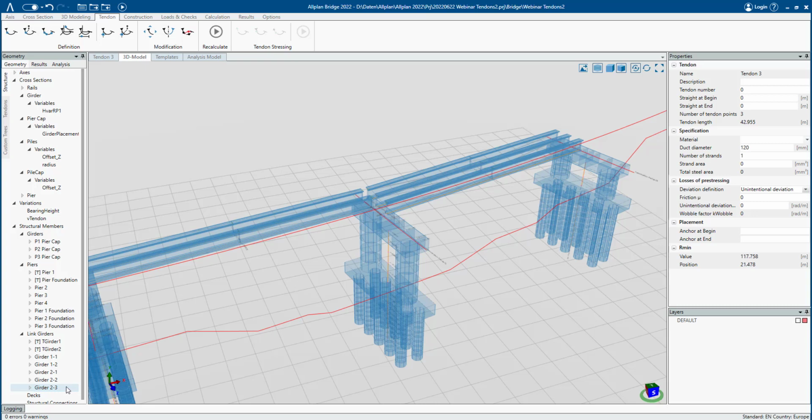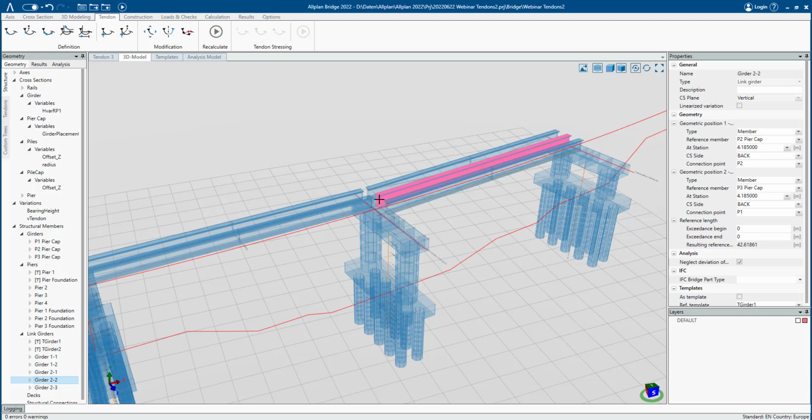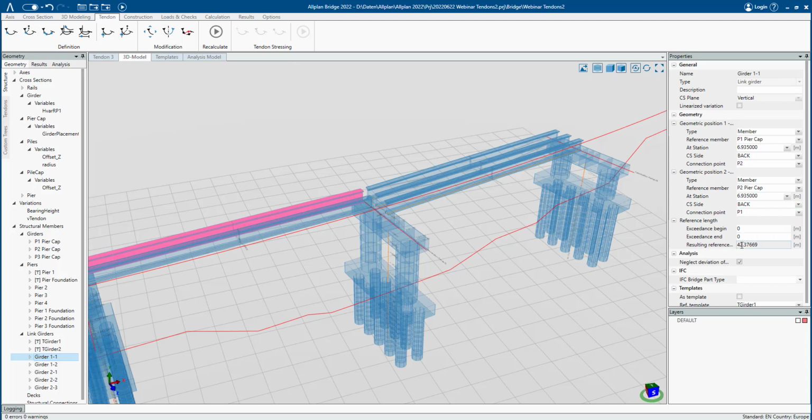Or also, if you want to adjust something or fit something, for example, I have this girder here and I want to use this girder in a different place. And focus here, we have a 42 meter span distance on this length, and when I look at this girder, it's also 42.16. So let me have a look. Yeah, 42.37 and so on. So there are slightly different distances in here. So what if I want to have this girder not here, but placed here actually?